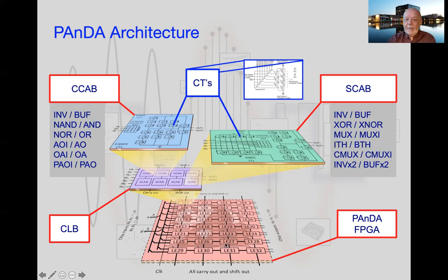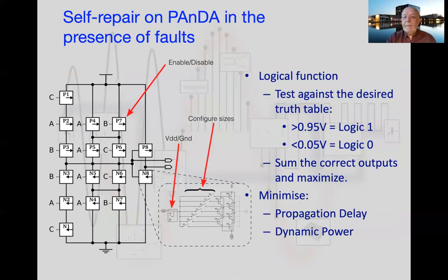So what you'll see now is, rather than what we're used to with an FPGA, we're actually doing configuration down at this level. We've got much more tight control over the configuration of our PAnDA architecture, which hopefully will allow us, post-fabrication, to deal with variability across the transistor. So if we've got a transistor which has got a slightly different characteristic, we can fine-tune that. We can fine-tune that by doing that. Okay, so let me show a slightly different use of the PAnDA device.